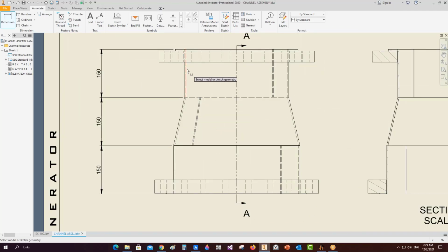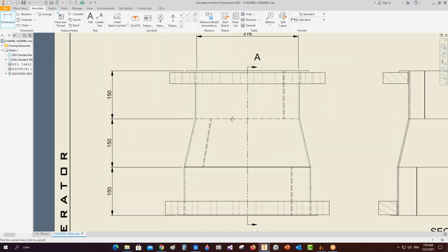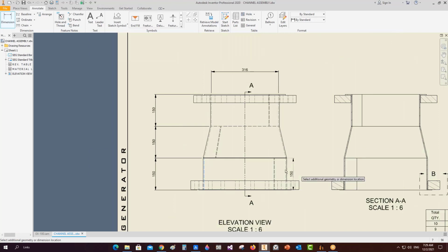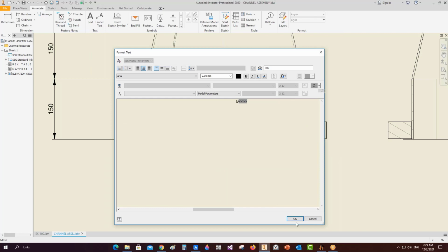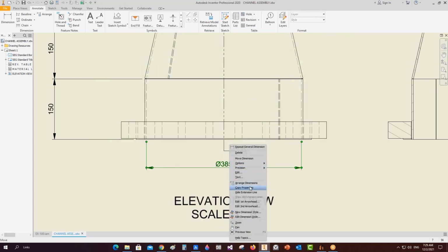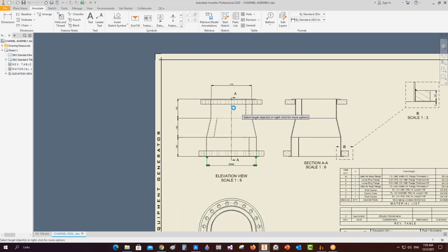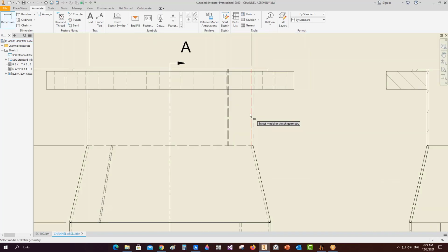Okay, define the inside diameter, for example, if you would like to make it like this. Okay, the inside diameter here. Like that, and let's add a text before it, which is 5, and copy it forward to this one. Let's add thicknesses.